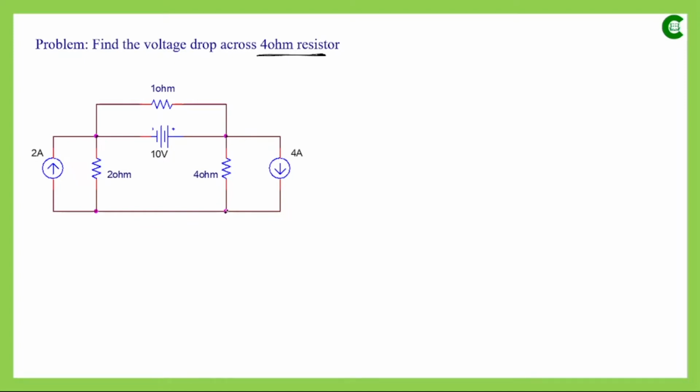Now suppose we connect this node to the ground, so this node can be taken as a reference node. That means we have two more principal nodes where we can apply the concept of KCL. So in this circuit we have 4 meshes and 2 principal nodes. So we will go for node analysis since the number of nodes is less than the number of meshes.